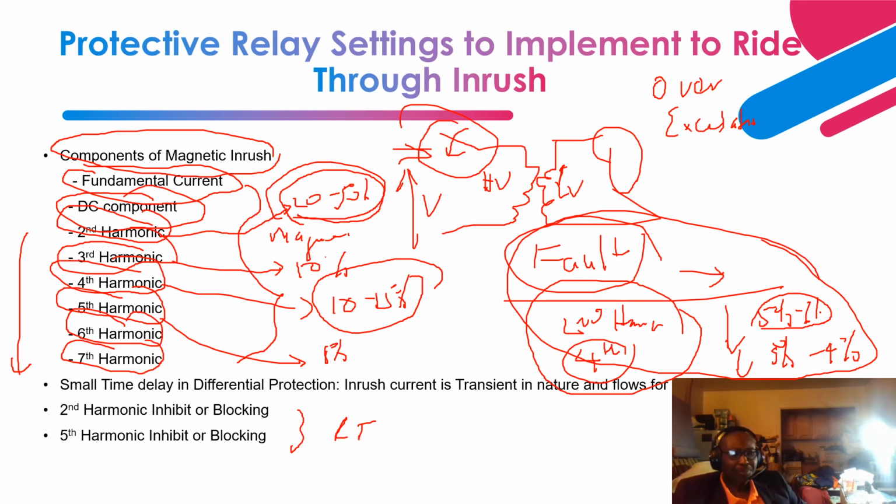So I'm energizing this transformer, and I have a third harmonic and the fifth harmonic, the odd harmonics: the third, the fifth, and the seventh. How do I distinguish between an inrush condition that has such components and an actual overexcitation condition that can saturate my core and create heating?